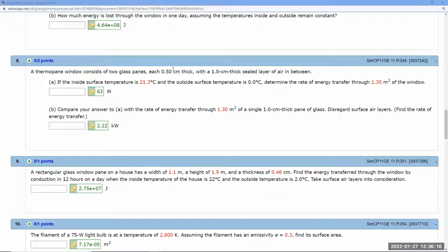You mean that you have 3 layers. But actually the thickness here, you multiply by 2, actually. But because both are the same glass, you have to use L over K. L1 over K1. If 3 layers, then L2 over K2. But since the glass is the same thickness, you can combine together. So you are able to find this is what we call a series.